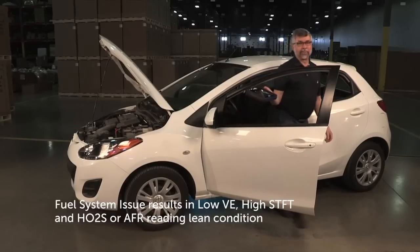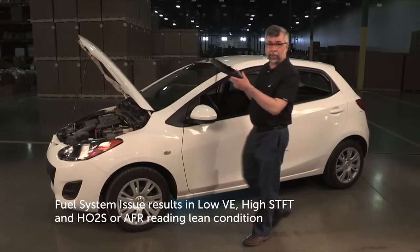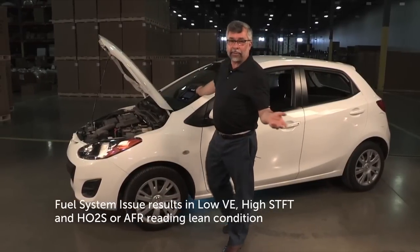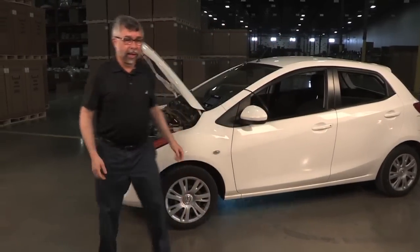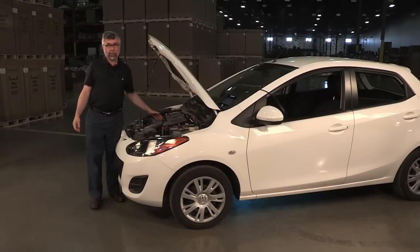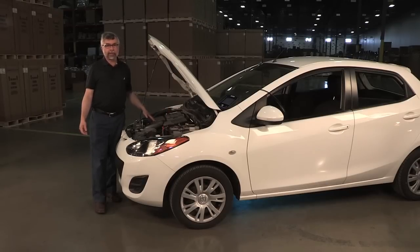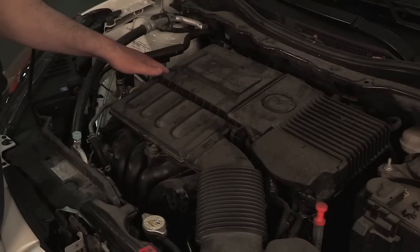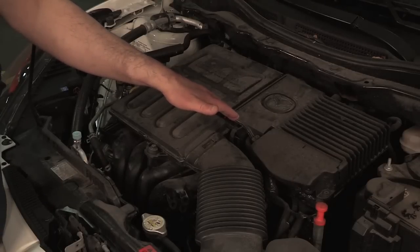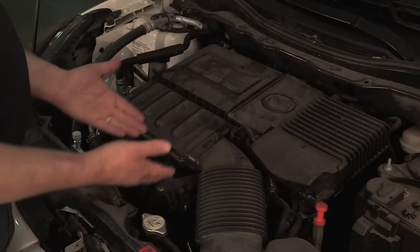You could have a fuel systems issue if you have VE test results of a low VE and a high short-term fuel trim with HO2S or air fuel ratio reading a lean condition. If my short-term fuel trim reads high and HO2S or air fuel ratio read lean, you have a fuel-related issue. This could be as a result of a dirty fuel filter, low fuel pump pressure, low fuel pump volume, or a restricted injector flow, limiting power, creating misfires, hesitation, and other drivability complaints.